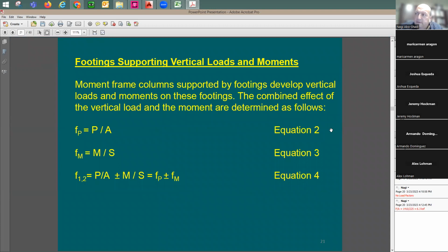All right. Now, the previous footing was just supporting vertical load. Now I may have vertical load and some moment. And we discussed the source of a moment coming to some gravity footings. We said it could be because of some eccentricity, maybe because we have a corbel. So we have more than one reason to have moment at the interface between the footing and the soil. So we have here 2 sources for the stresses. One is given by the axial load and the other one is given by the moment.